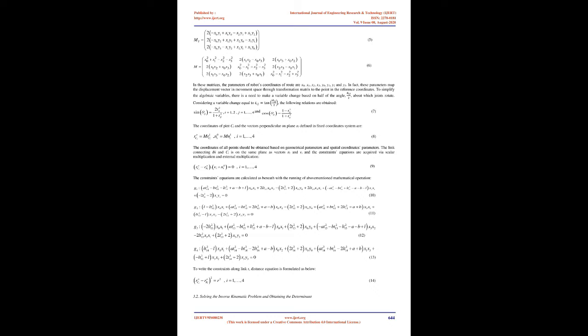In inverse singular points, the robot tends towards infinity when being moved from Cartesian space to joint space, and this makes the transformation from the former to the latter impossible. The limit concept, in fact, offers a formulation based on which the inverse transfer function from Cartesian space to joint space turns into a bounded value. In the end, mechanism parameters effective in the form of the workspace are identified, and the best of them will be selected for the expansion of the workspace.